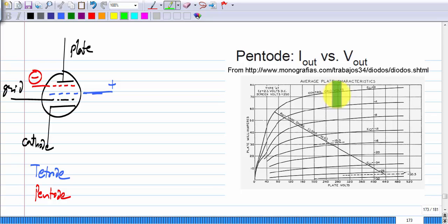Remember, before we did anything, we tried to look at what the characteristics of an amplifier should be, and we found that Y22 should be very small, close to 0, and you can clearly see that Y22 of a pentode approximates that, whereas that for a triode did not do it at all.